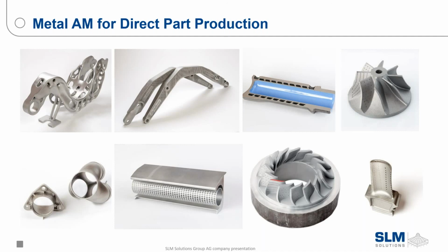So with process parameters, SLM Solutions is very different than anybody else, in that we offer open parameter sets. We will give a stainless steel, titanium, aluminum parameter set. Those parameter sets are open and they can all be edited. We know that the parameters you get might be 90% of the way there for your particular application, whether you're trying to push the limits in size, speed, and so forth.